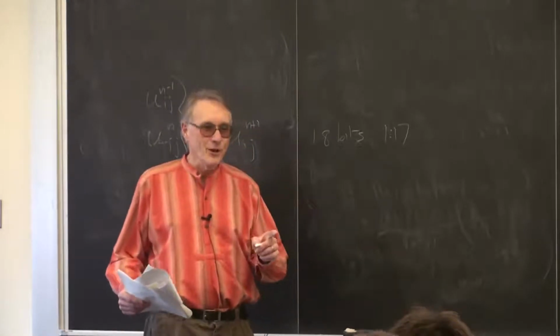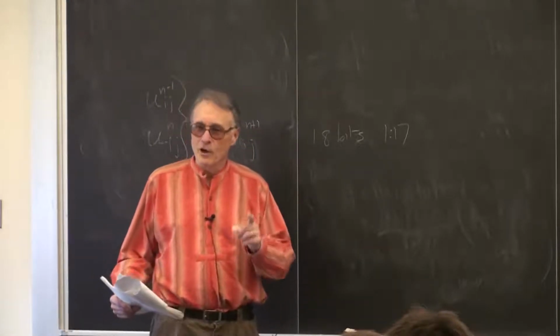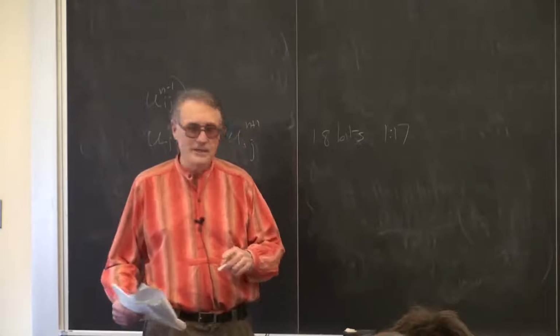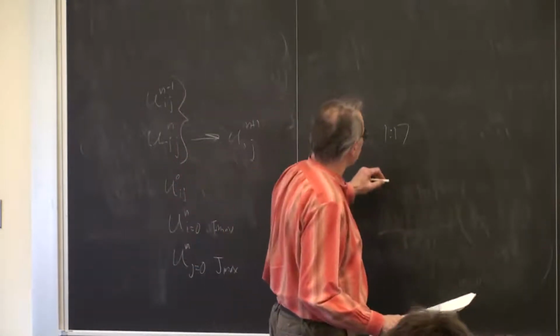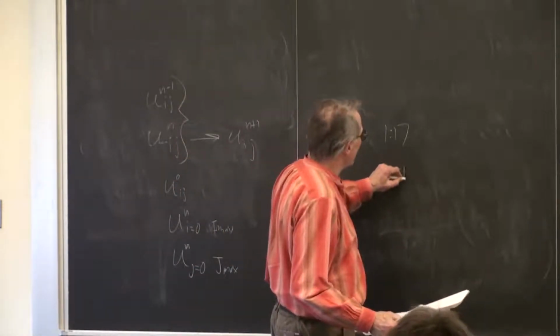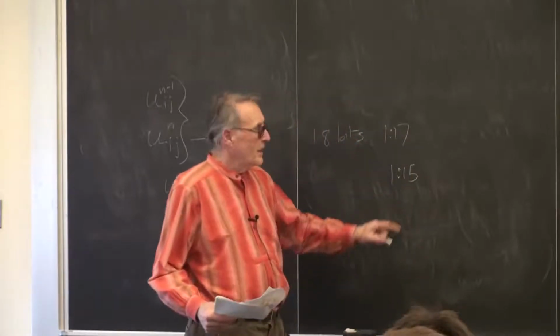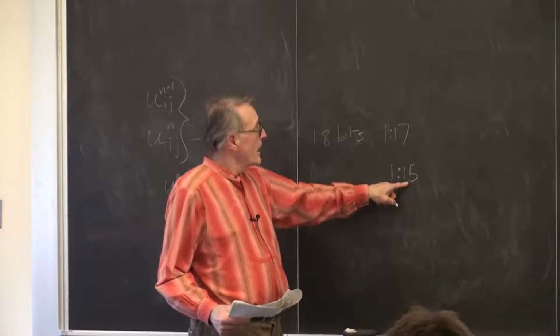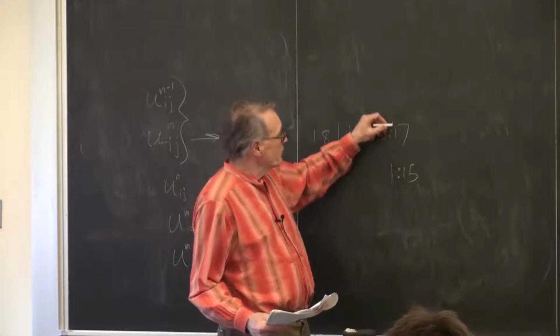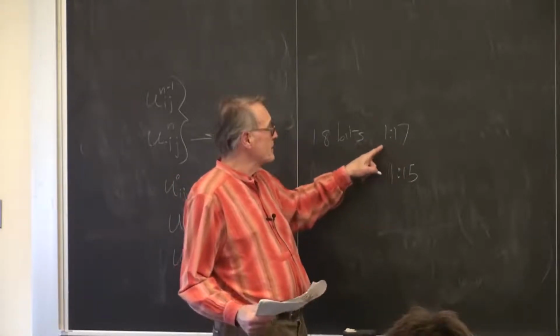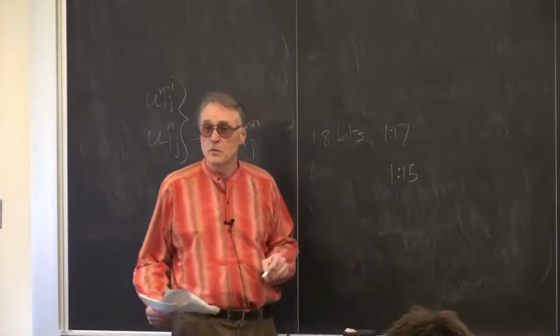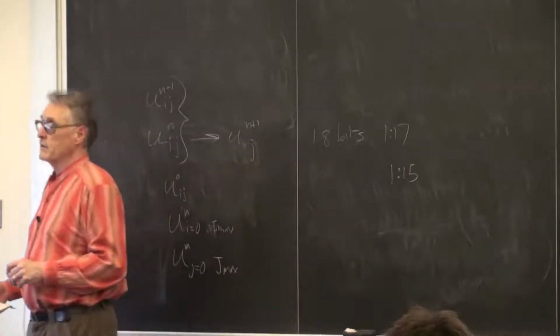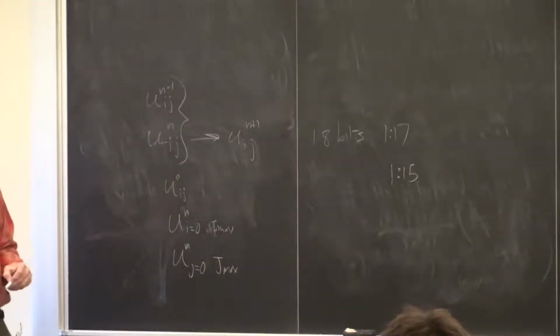happens to be very close to what the audio codec needs to operate. It expects 1.15 format, a sign bit and a fraction. And so all you have to do for the conversion is to truncate the lower 2 bits off of your calculation if you use 1.17, and you get a signal which is suitable for feeding into the audio codec.